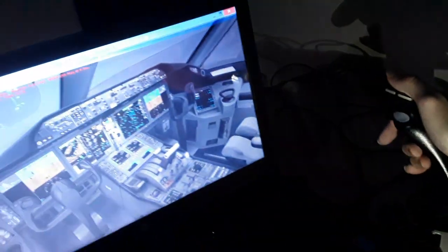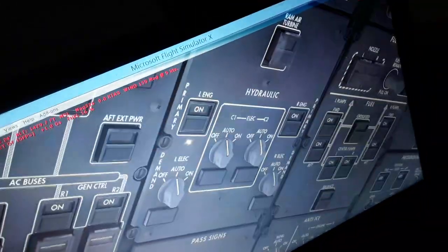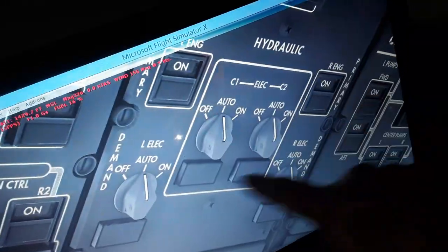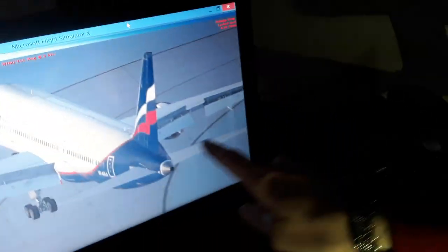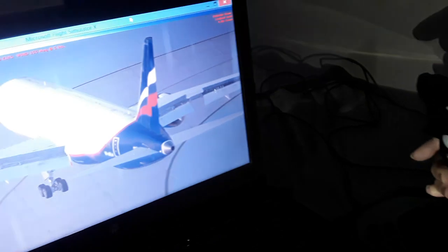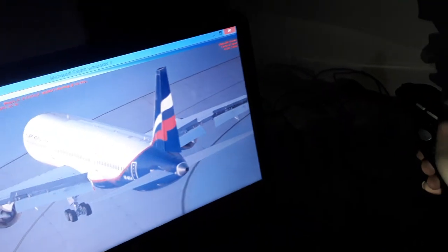So we have similar modes in the Boeing aircraft like this. You can see the flight control computers. If you have a failure over here of the Boeing aircraft in the hydraulic system that controls the elevator of the aircraft, you can see here is the elevator, the horizontal elevator. We need it to climb and descend the aircraft like this. Pull the side stick up, we climb, pull the side stick down, we descend. Also the rudder.